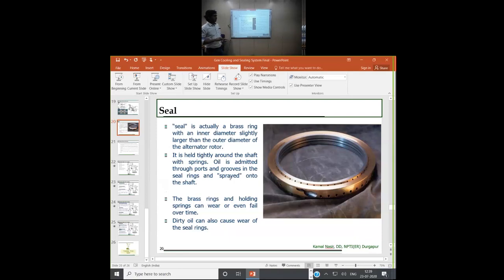And slip rings, because in the excitation system when you provide DC power, polarity is constant, but the generator is rotating. So you need the slip ring to provide that. Sometimes you see when you are taking output also from a generator, R Y B phase, you need slip rings. It is in reference to that. It might be covered in today's lecture. But still, if you have doubt, I will clear it again. But I think it is clear if you go through the video that will be uploaded.